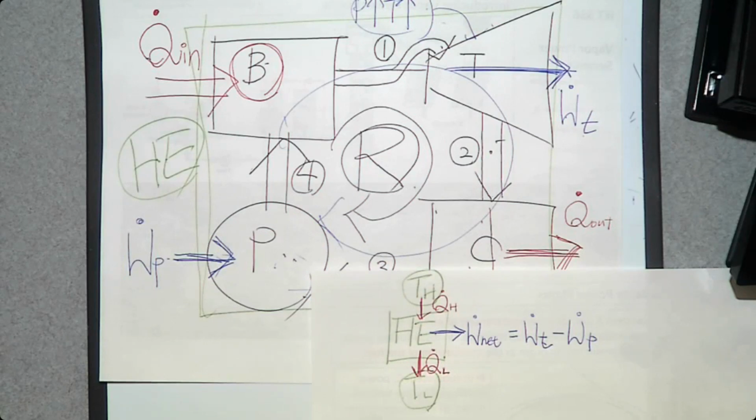They watch the conditions at each state, like what is the condition at the turbine inlet, what is the temperature of the steam, what is the pressure of the steam, what is the flow rate of the steam, and they also measure the same at the exit of the turbine, at the inlet of the pump, at the exit of the pump, and make sure that all the values are steady state. If one goes wrong, then you need to stop it or do something to fix it. When you cannot fix it, what's going to happen?